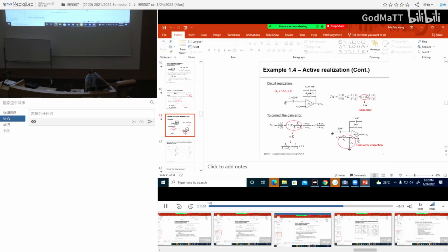resistor divider network. So this is still an inverting amplifier configuration, except now the input, instead of going straight into the positive input, goes through a scaling network. So the value at the input is RB divided by RA plus RB. With this I can scale the K factor.